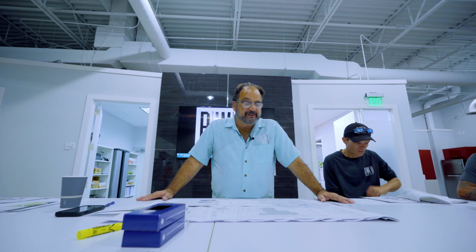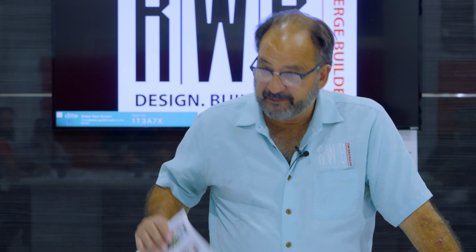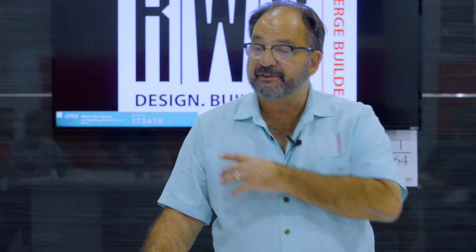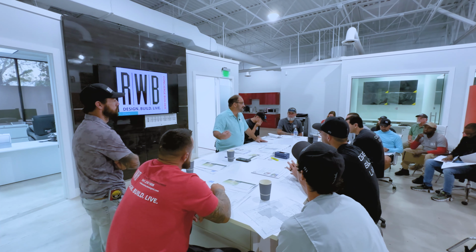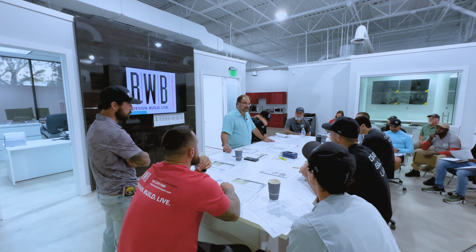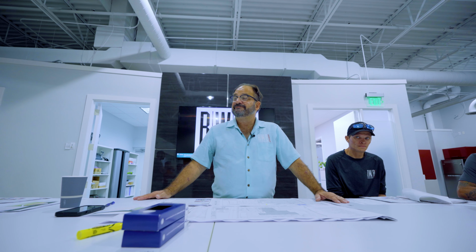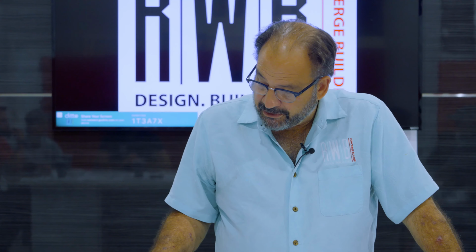Okay? We usually do a perforated driveway system, where if you can picture this drainage field here, you can picture a drainage field under the entire driveway, where the entire driveway has 18 inches of rock and the water goes through. We do that in addition to everything that the civil engineer does. It retains the water almost like a 100-foot long exfiltration field. Okay? We always do the most.